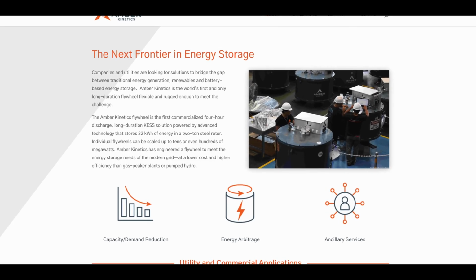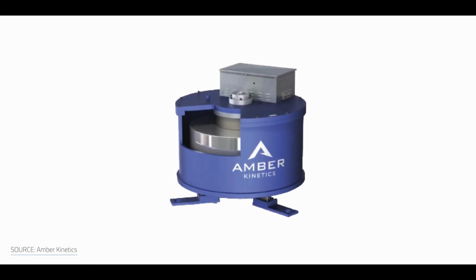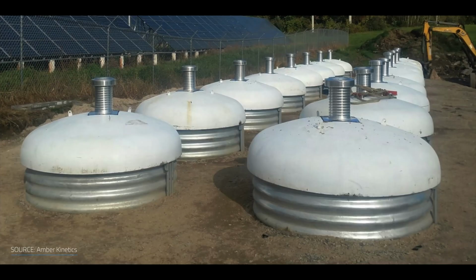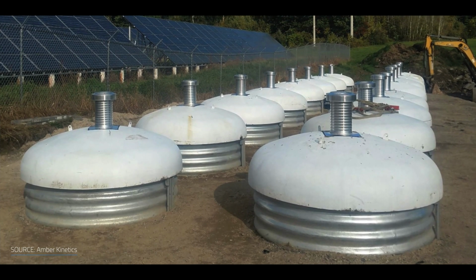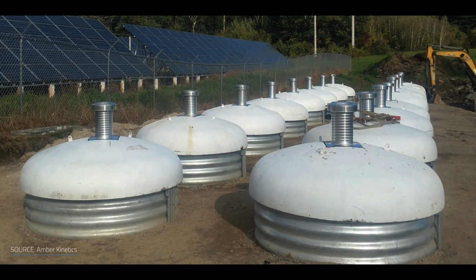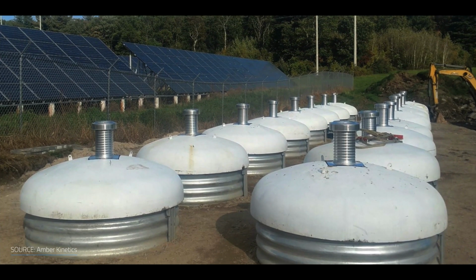Another company playing this game is Amber Kinetics. Their all-steel M32 model can provide 8 kilowatts of power for 4 hours, achieves efficiency higher than 86%, and offers 11,000 cycles. In 2018, the company, in partnership with West Boylston Municipal Lighting Plant, commissioned a 128 kilowatt, 512 kilowatt hour flywheel energy storage system in Massachusetts. This project is integrated into a grid-connected solar array and has already discharged 116 megawatt hours.